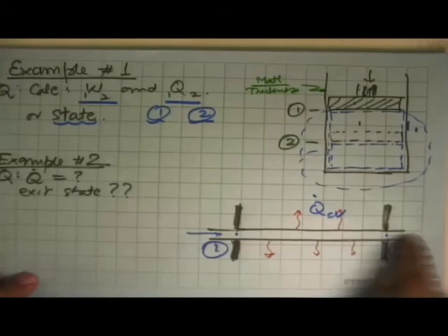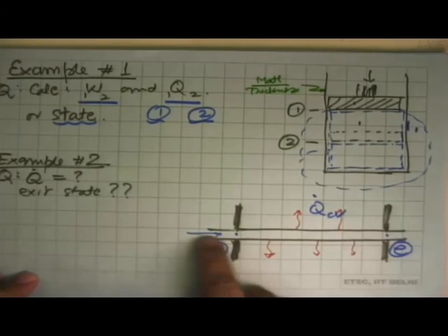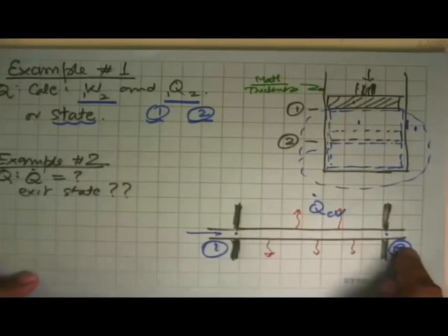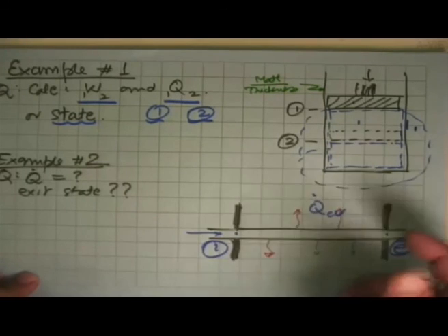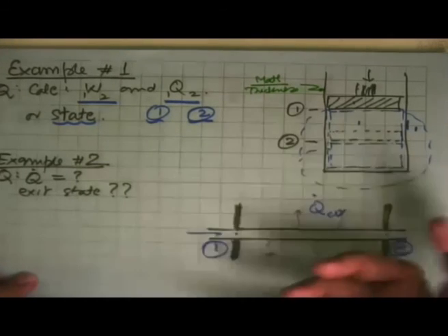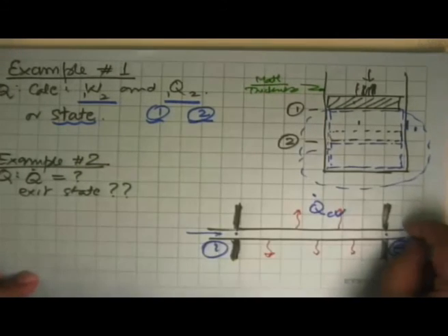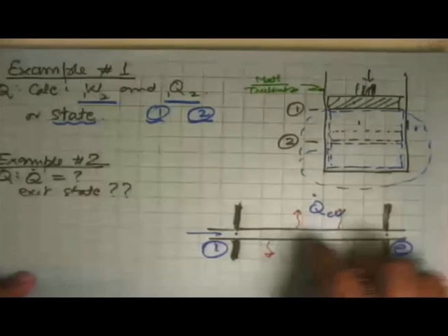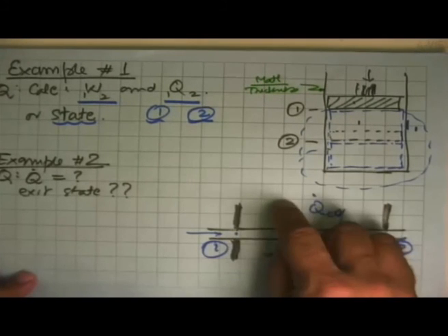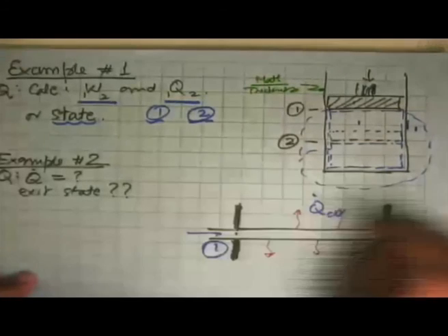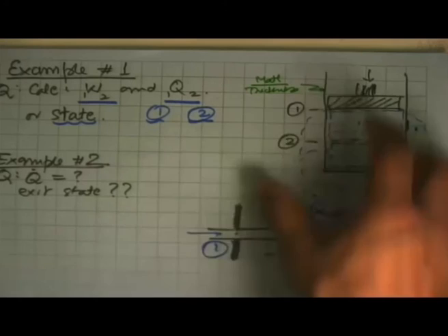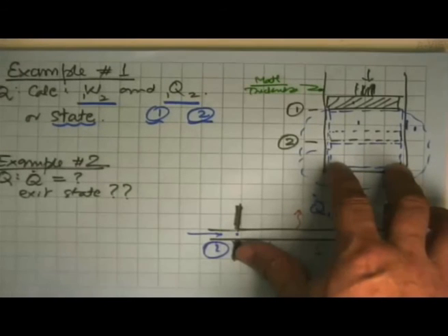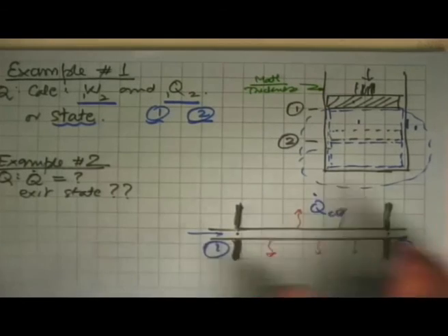If we know the state that it is going to be here, we say, look, this is the inlet pressure and temperature, this is the outlet pressure and temperature. We have to select a tube which will not rupture at the highest possible pressure or temperature. And so let's see what materials we can take. What are those materials which are compatible with this substance, and then, within that, how thick should it be, and all those decisions start to come in. So what I'm trying to say is that the basic thermodynamic calculation is the starting point for the entire mechanical design of the application.